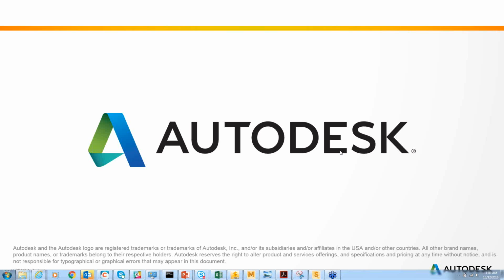What type of CAD files are you able to save with the direct geometry modification tool? At the moment, it's limited to SAT, but we are looking at adding STEP files in a future release. We have all the other formats available, but we started with SAT at the moment. IGES we will probably not do. IGES tends to be a very poor format, just want to say.